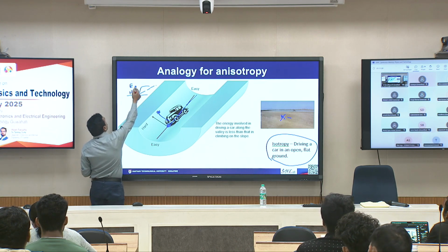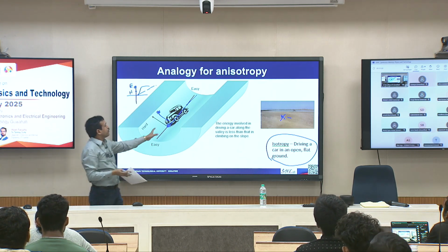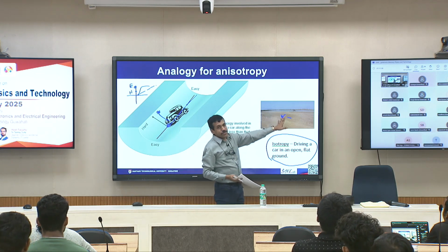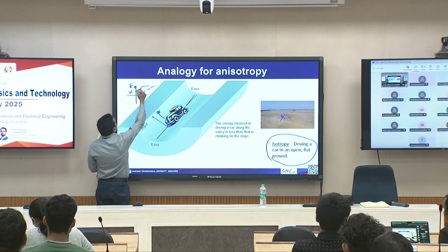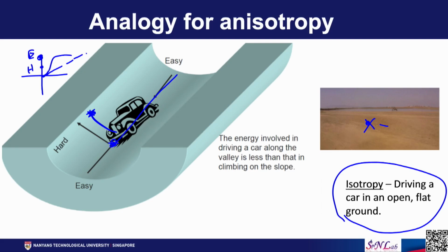So, this is equivalent to retention of magnetic moment. Here I am talking about retention of car in its initial position, but in magnetism we are talking about retention of magnetization. In the case of easy direction, you apply magnetic field, you have certain magnetization, and if you remove the magnetic field, you are almost there. So, you retain much of the magnetization. This is a property of easy direction. In the hard direction, you will almost retain nothing or a little bit. Depending on the property of the material that you make, in the hard direction you will basically retain much less.